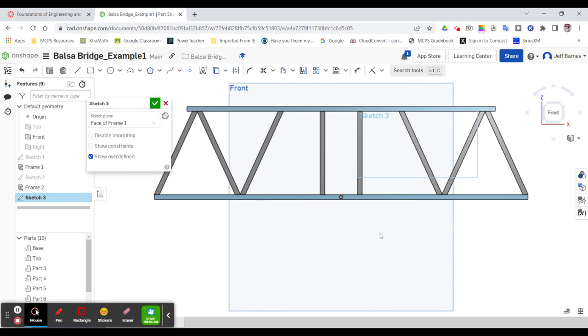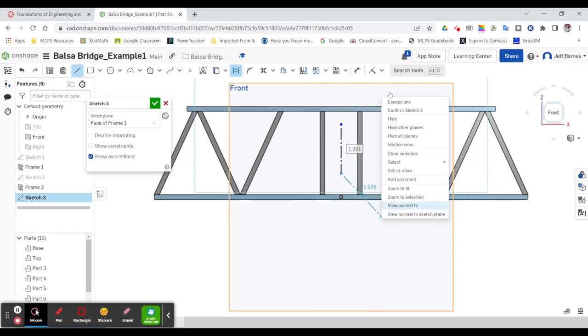And so I'm going to draw them as rectangles. So again, I'm going to start with a line of symmetry, so I only have to do so many squares. So I'm going to select my line, select my construction, and again, use my midpoint here as just a line of symmetry. So that's why it doesn't need to go all the way to the top or bottom. So right click, escape.